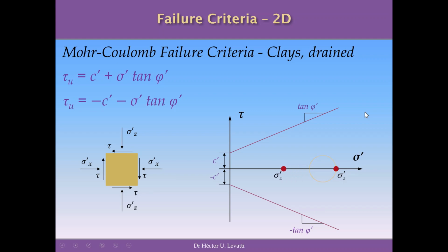If we reduce the value of the axial stress in the horizontal direction, and we are talking about reduction in here, we increase the size of the Mohr circle. So a reduction in stresses can produce a worse state of stresses in soil mechanics and in geotechnical engineering. So this is important to understand.